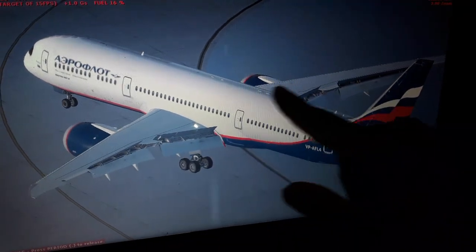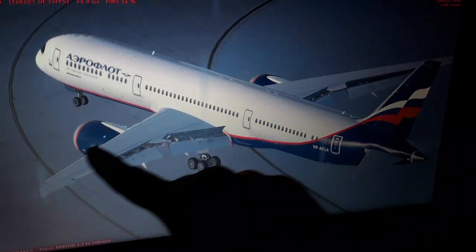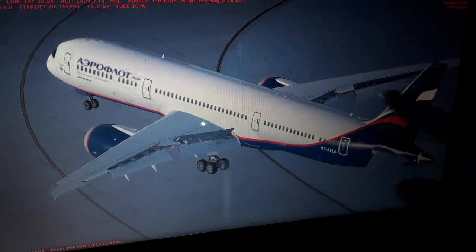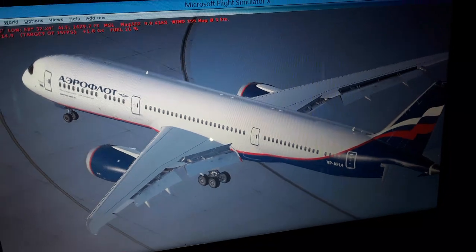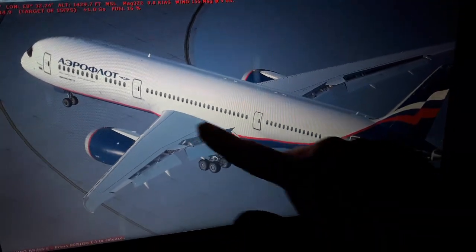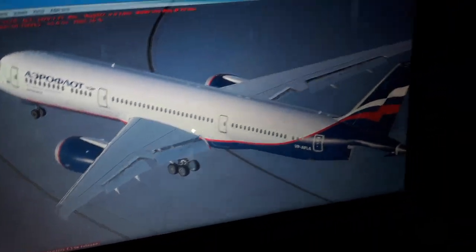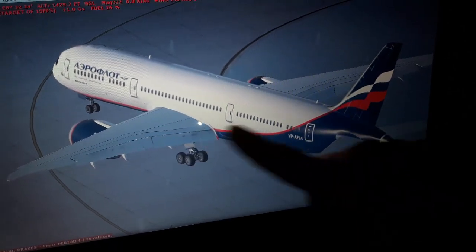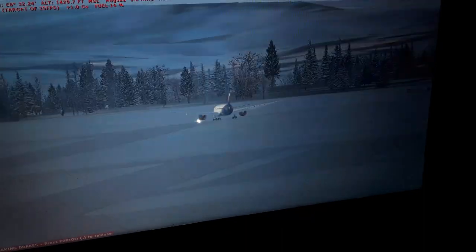Over here is where the maximum aerodynamic lift occurs in the forward wings. It is also the position where the center of pressure is moving back and forth when we fly. Also the stall will begin in the top surface of the wings when we fly. The airflow becomes detached from the top surface of the wings, and we have the wings and the aircraft stalled.